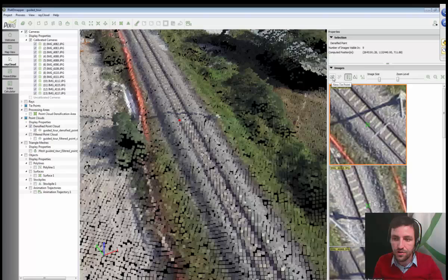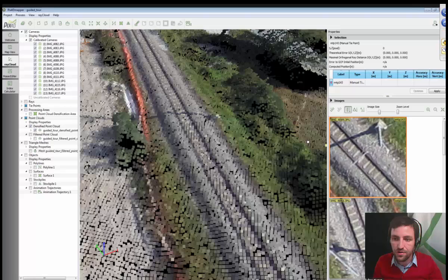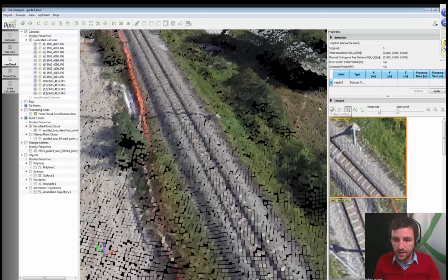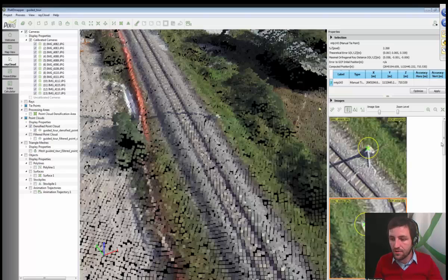In this box, when you click new tie points, it will allow you to generate one of these tie points that were used for the calibration, but this one will be taken much more into consideration, and it will very likely help the software to better align the images in that area. For that, you will need to, as I mentioned, click on this Add New Tie Points, and then you have to click in at least 2 images the exact same location of these tie points. Let's try to click on top of this tower.